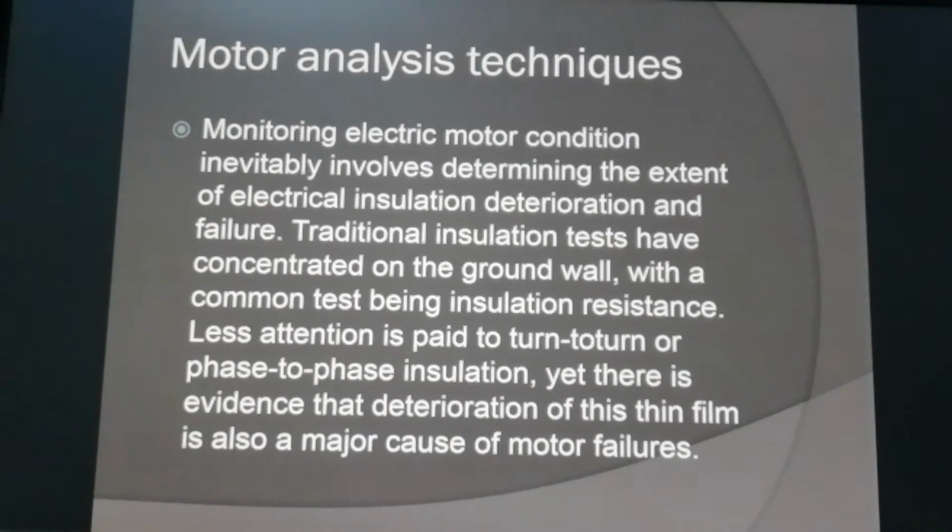Okay, this one is the motor analysis technique. Monitoring electric motor condition inevitably involves determining the extent of electrical insulation deterioration and failure. Traditional insulation tests have concentrated on the ground wall, with a common test being insulation resistance, and less attention is paid to turn or phase-to-phase insulation, yet there is evidence that deterioration of this thin film is also a major cause of motor failures.